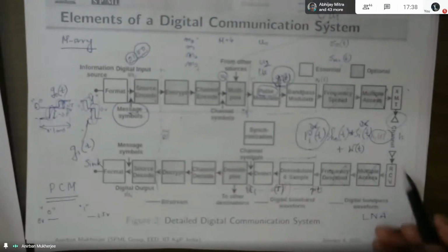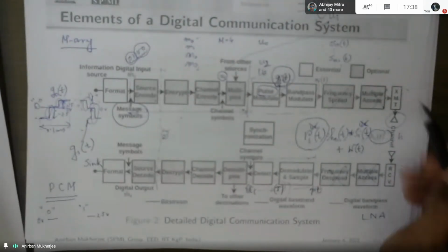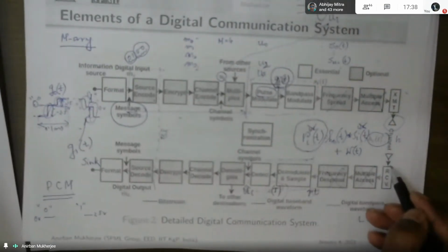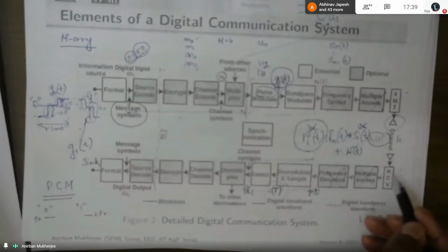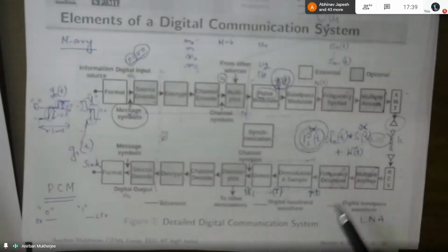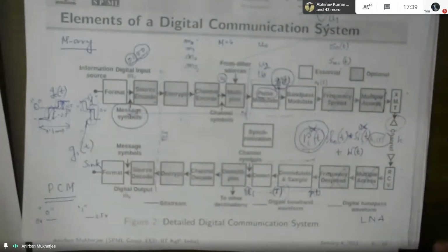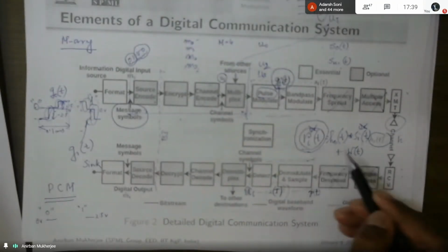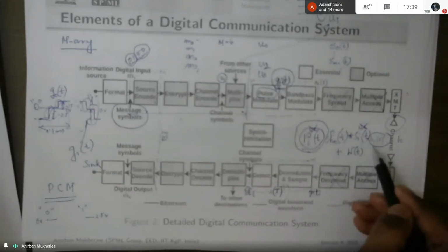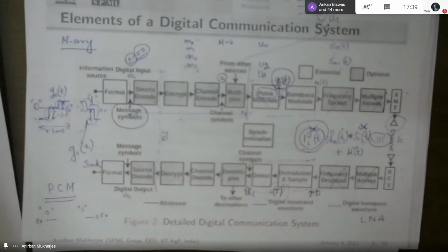So finally, you are doing up conversion, then you have r up-conversion, ri up-conversion, and you have down conversion, LNA and all these things, so that from there you are getting ri. Both up conversion and down conversion are there; I am just removing that business. So I have directly ri(t) equal to hc(t) convolution si(t) plus w(t). Is it clear?